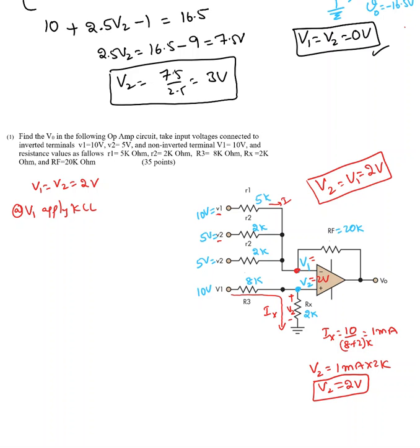Okay, I'm going to take this as I1, I2, I3. Only 3 currents are coming over there, and as usual I'm going to take this as IF. So I1 plus I2 plus I3 equal to IF. What is I1? I1 is nothing but 10 minus V1. So the voltage at this point is 10 volts. Voltage at this point, these four are the same points, same node. So the voltage on this red line anywhere is V1, which is 2 volts.